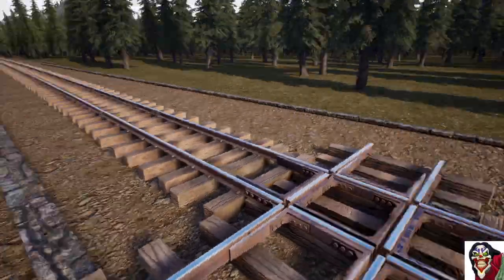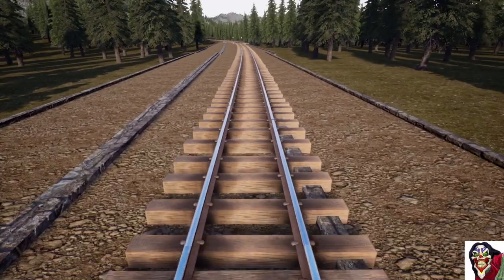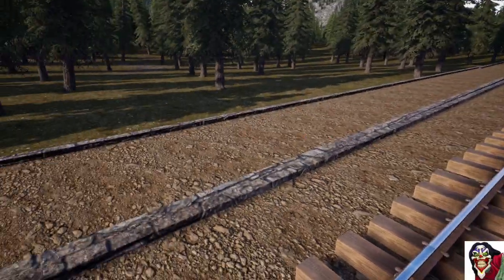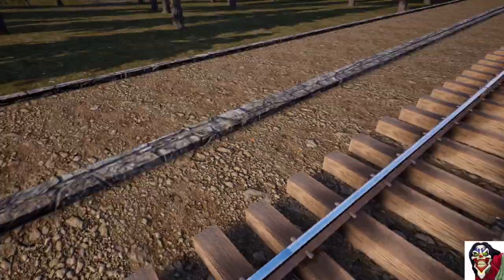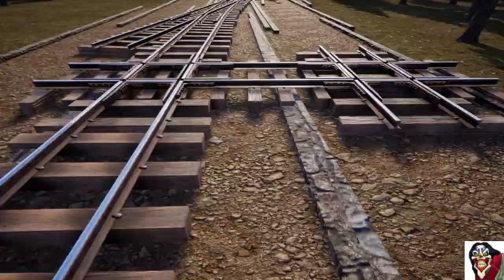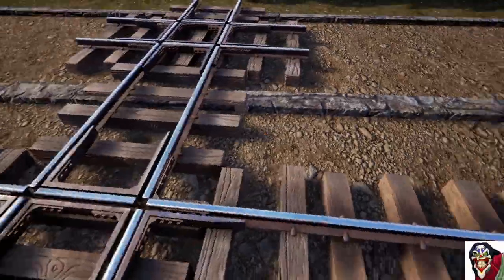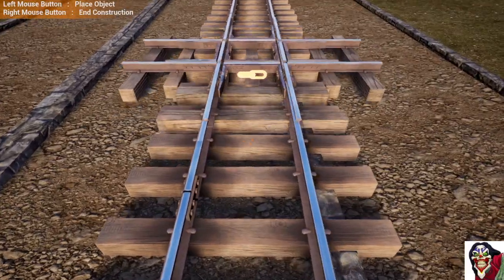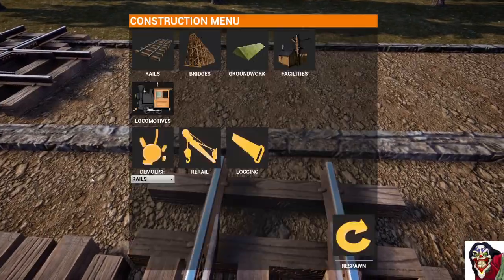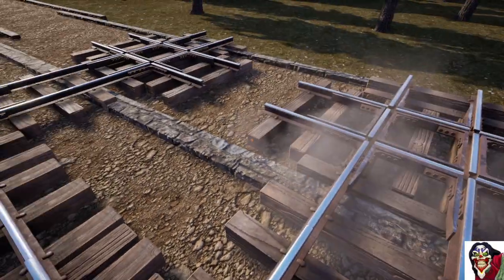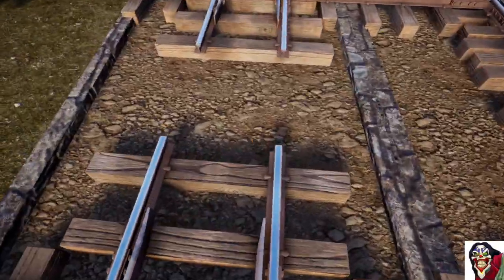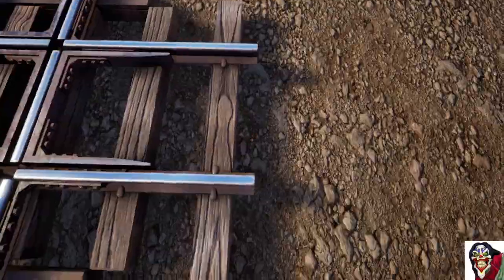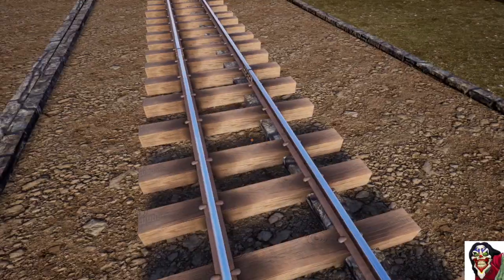The only way that you can get this to meet up is to come along on this track and transpose the control points from here over to where this track would be at this spacing. So what we do is we come along and get them to stand, pop back under our feet like that, and we build this one here. Now when we connect from this set of control points to this set of control points, it will give us the correct spacing to the track.